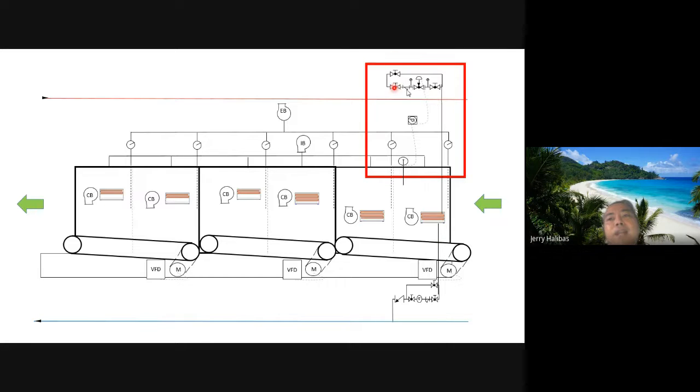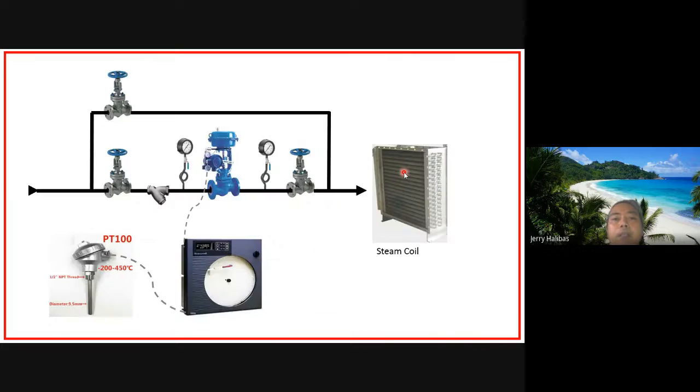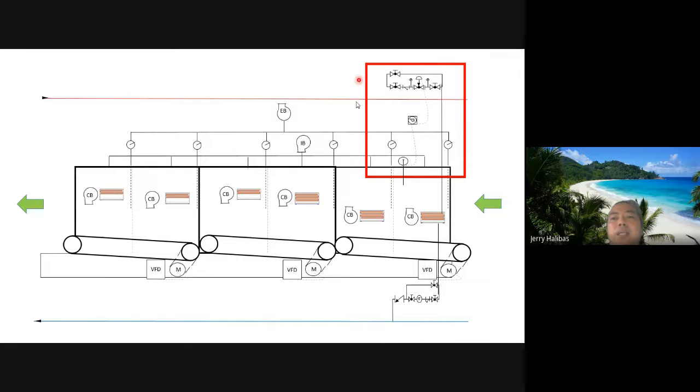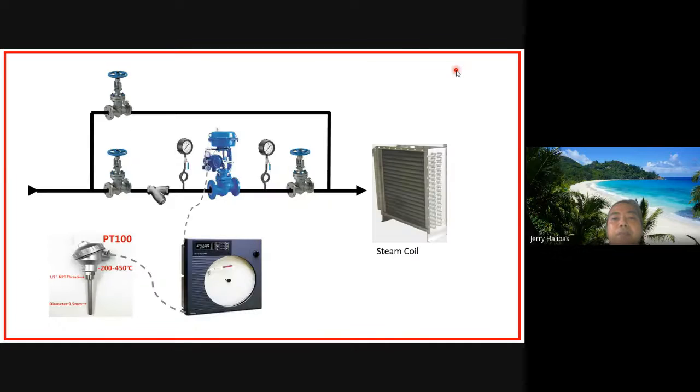So there is a valve arrangement here. Then there is a temperature controller, and your temperature sensor. It would be an RTD. Okay, so the circular and rectangular red component is the proportional control valve, or pneumatic control valve that is proportional.